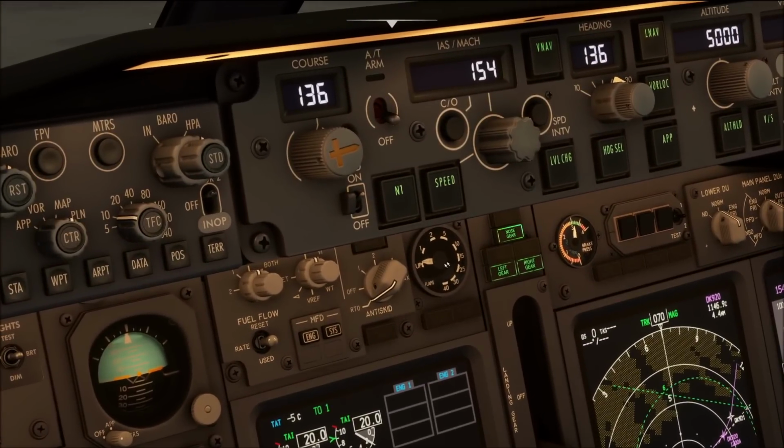Now closely look at the flap indicator to make sure that the flaps are moving smoothly. This is the only situation in which, if the flaps should ever stop at a certain position, you would reselect the flap lever to the position that matches the actual flap position the closest. So in the air, if you do have a flap malfunction, never ever just move the flap lever without the checklist instructing you to do so. Or in other words, as they love to say, there are no memory items associated with flap problems.